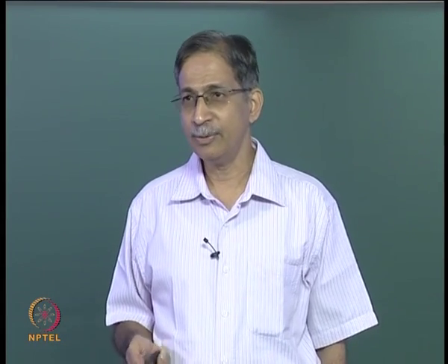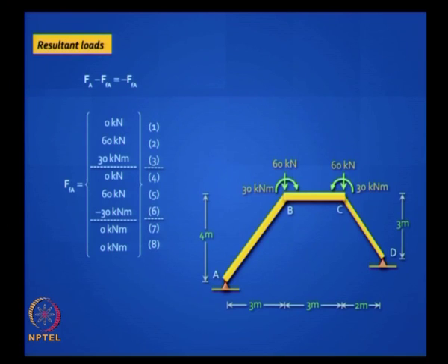Right, you can draw a sketch. Look at this. This is your resultant load vector. FA minus FFA. FA is a null vector because there are no nodal loads in this particular problem. You had only a UDL, and so FFA is given there. Put a negative sign to it and interpret those results.